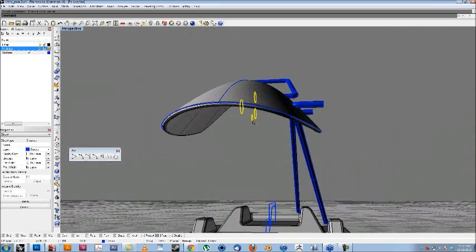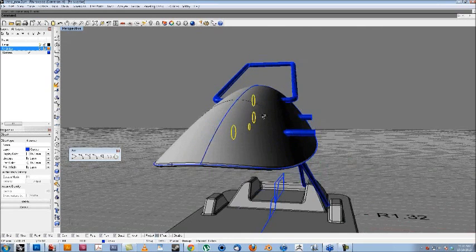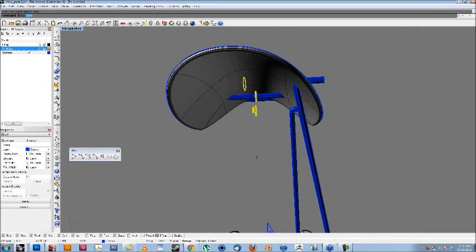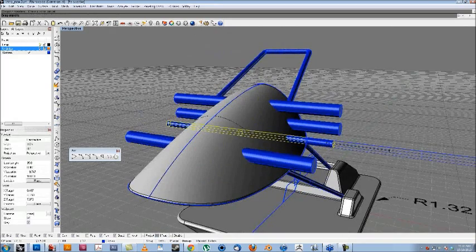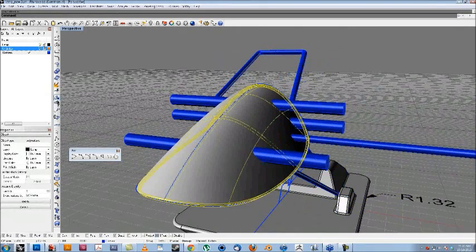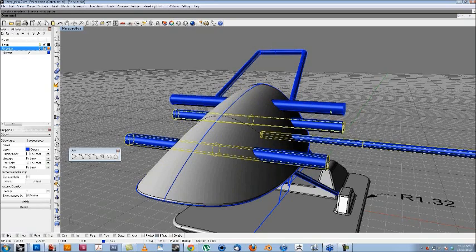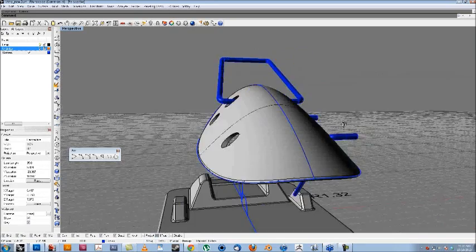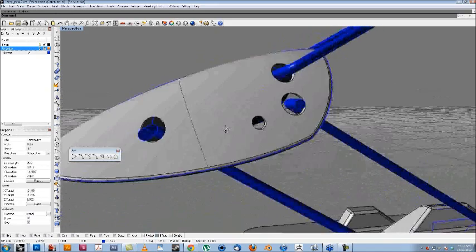So one more thing to do to this lampshade, and that's to extrude it. Extrude the curves that are here, and these are going to act as Boolean operations on the lamp. So we'll take the lamp itself, do a Boolean difference, and then we can delete those, and you can see now those are passing perfectly through the center.